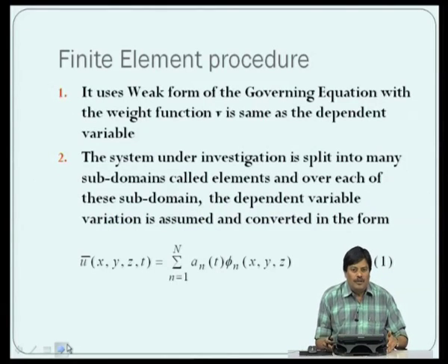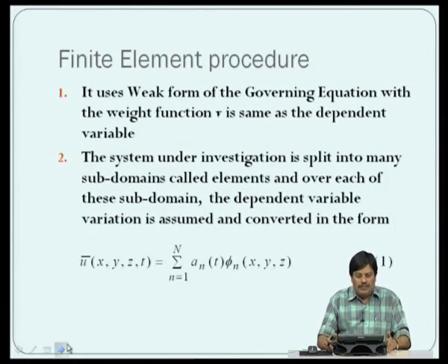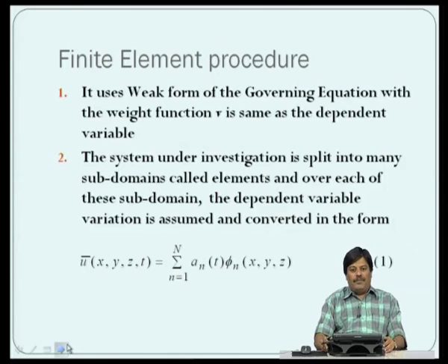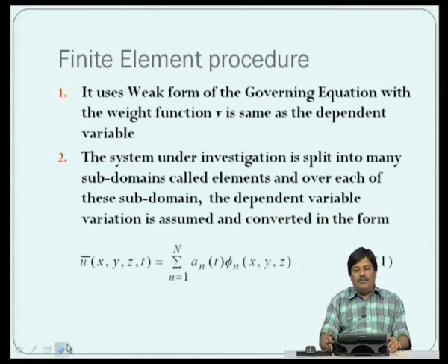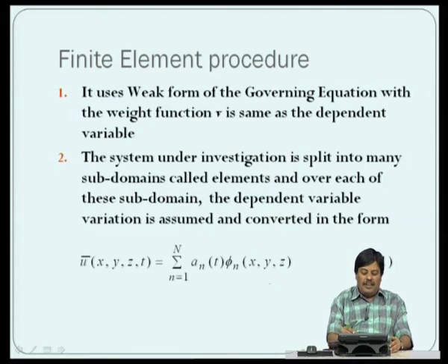So, just to give a summary of what we talked about in the last class, we said that finite element uses the weak form of the governing equation with the weight function v, which is same as the dependent variable function which is given in equation 1 here.